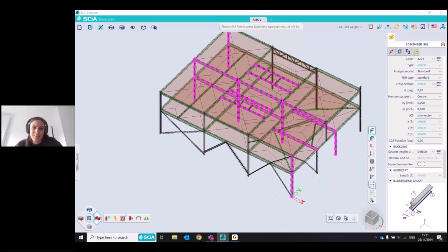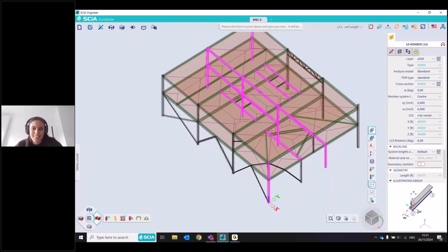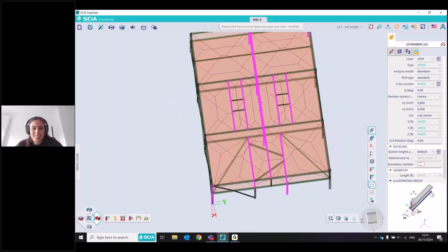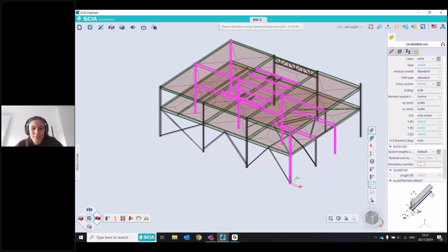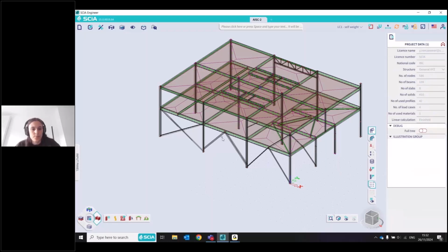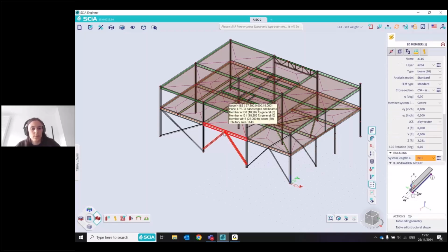This project doesn't really have a standard column in it. It's quite variable, so I would basically have to look at about every single one of them in particular to define their systems. But it's really important because, for example, here for this one, this bracing will be seen as a support for buckling, whereas the bracing maybe doesn't take any compression.